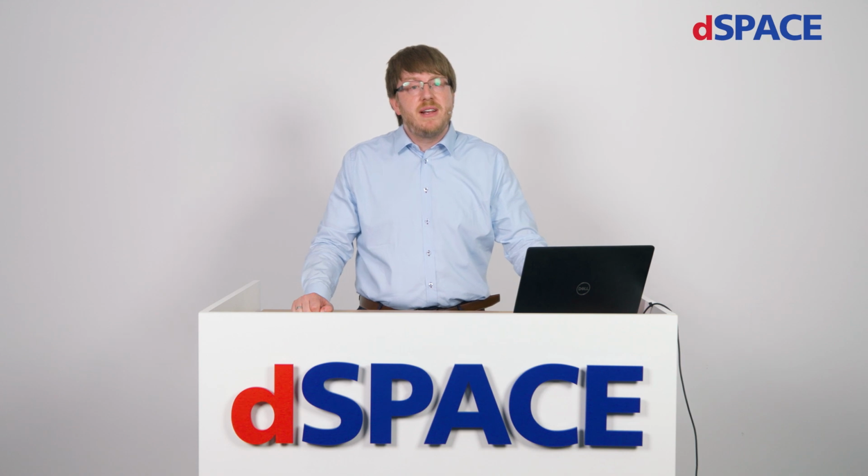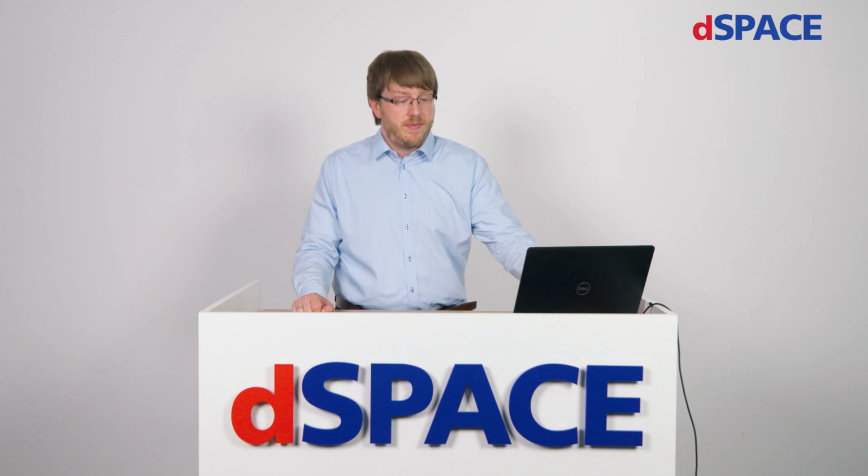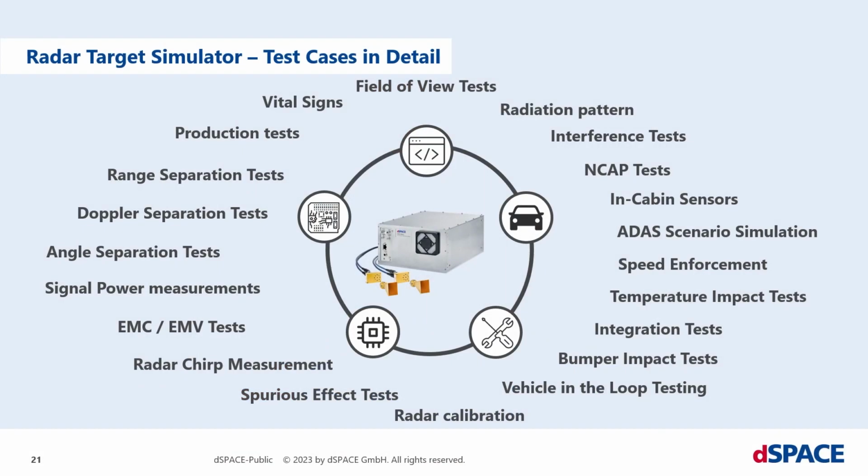Now, let us dive a little deeper into a specific radar test case, target separation. This is a collection of test cases where radar target simulators are used during the life cycle of a radar. Depending on the application of the radar chips and sensors, a collection of these tests has to be performed. In the previous slides, we have learned that the range resolution is a key specification of a radar sensor. High efforts are spent by Tier 2s and Tier 1s to lower this resolution for improved performance in ADAS and AD.